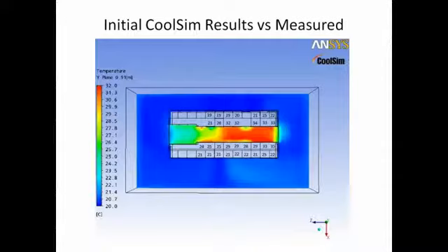It assumes a lot. It assumes some defaults. And what you can see here in this first plot is a slice. We're looking down at the data center. Here you have the nodes and the cooling units are here, and here are the nodes. It's a pod configuration, so it's hot in the center. The outer region is cold, and so the airflow goes out hot, out cold here, comes back around and gets pulled back through the servers and is hot on the other side.